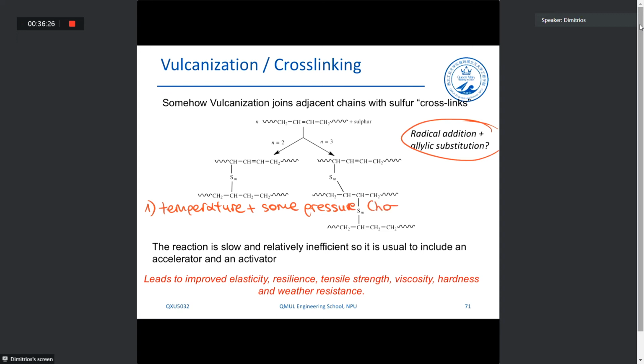That takes place in a hot press. Hot press essentially is this machine where we compact a sheet of polymer. Let's say this is a polymer. We compact it between two plates and we heat it up in there under constant pressure. Okay, so we apply a temperature and some pressure, or we apply UV radiation.